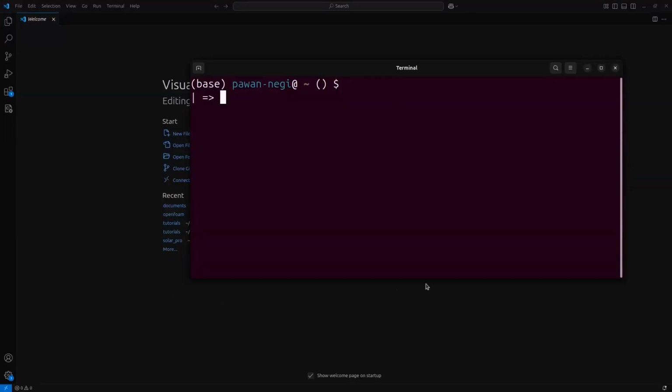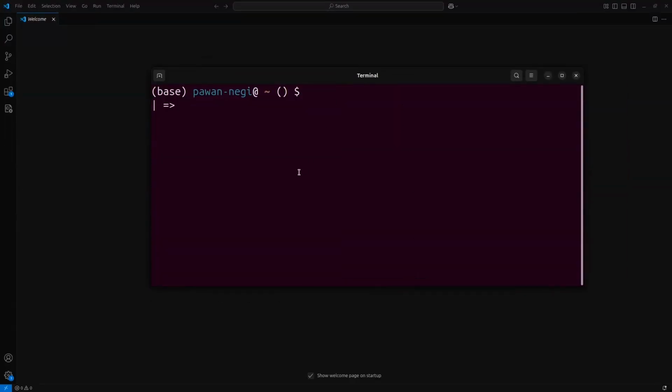Welcome back. Today we are going to use the rhoCentralFoam solver that is present in OpenFOAM. It's an open source software. This particular solver, as you may have seen in the introductory lecture, where I explained that rhoCentralFoam is a density based solver and it solves the variables, the pressure, velocity, and energy in their conservative forms. The conservative forms are density, momentum, and energy. Using that, we are going to simulate the shock tube problem.